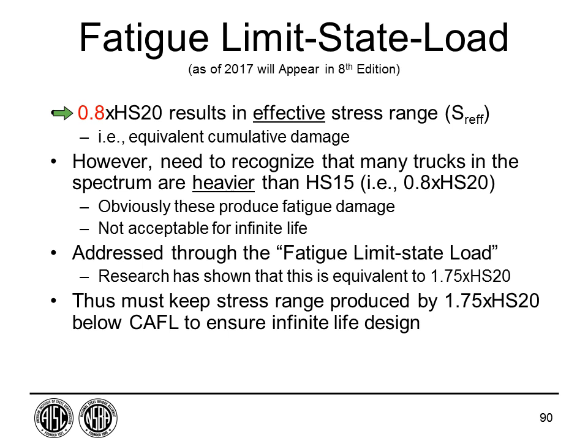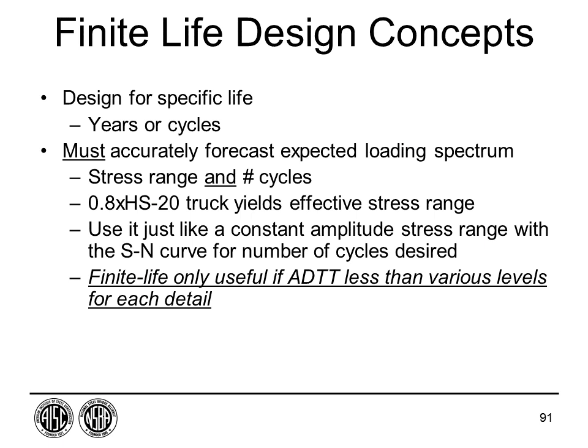If I want to have infinite life, I have to increase that load to reflect the large number of vehicles that actually are on the interstates that produce stress ranges that would exceed the fatigue limit. So I would use this for infinite life design. I can use the fatigue truck for finite life design, where I'm really concerned about a finite life and the damage accrued. Because remember, it's to give me the same fatigue damage. That'll show up in the next version of the AASHTO specifications.